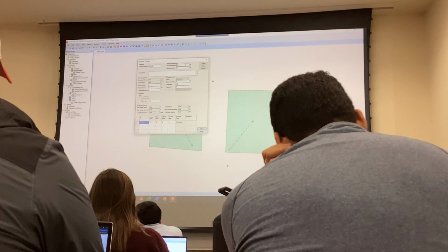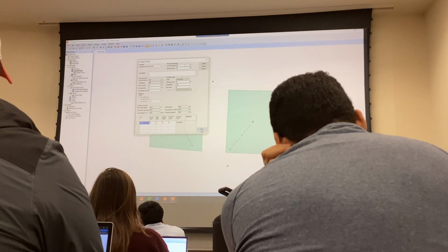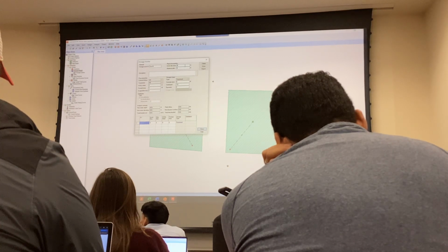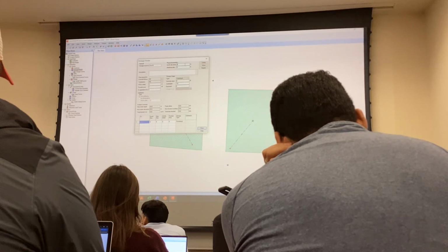So we are going to go through this one at a time. Okay? First things first. You have to have an invert elevation for your detention basin. So even when you draw it on AutoCAD, you have to have a floor, the elevation for the bottom of your detention basin, and it has to have some elevation at the top of your detention basin. Okay?